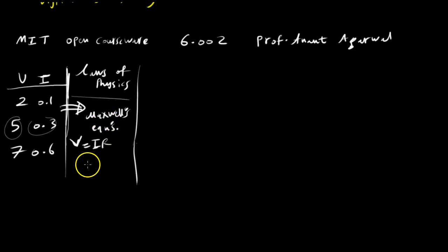So what this is going to do is give us certain curves. For example, if you plot voltage and current, the slope of the curve would represent resistance. And we can look at a certain point of this curve and say, okay, for example, at 0.1 amps of current we apply 2 volts of voltage, and there was some resistance, some slope, which represents the resistance. So that tells us the 3 quantities.